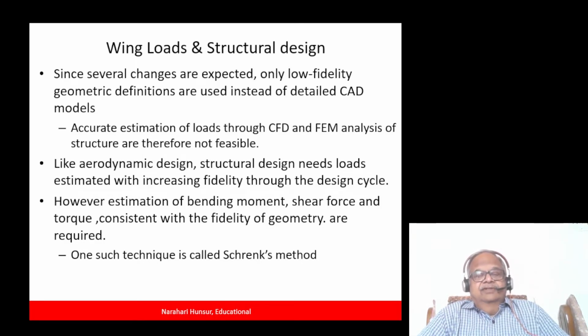And since the definitions are not accurate enough, CFD and FEM analysis of structure are therefore not feasible. Structural design also needs to be done at the same time, and they need estimated loads with increasing fidelity as the design cycle progresses. So initially it was enough for us to tell them that this is the maximum bending moment and shear force which is going to come at the root, and they would come out with a design. Either say yes or no, basically go or no go for our design.